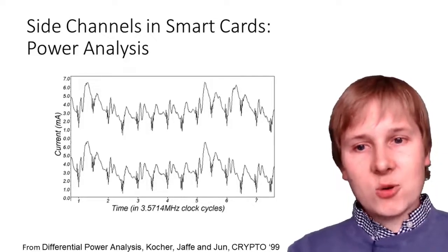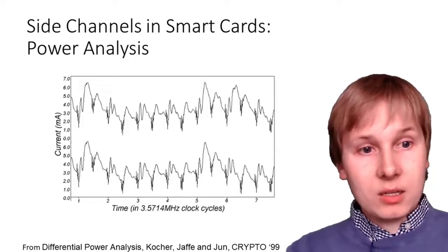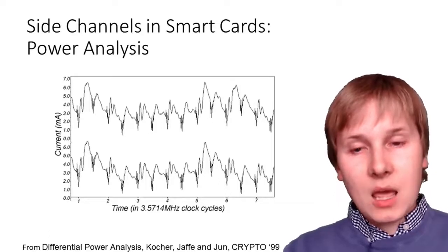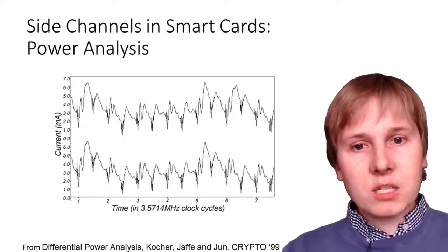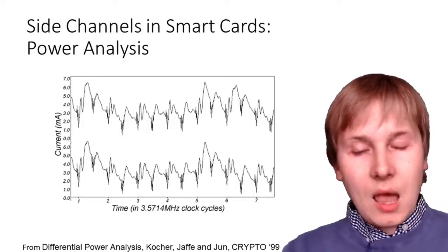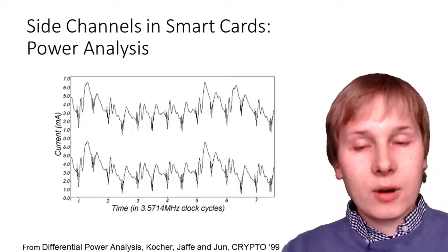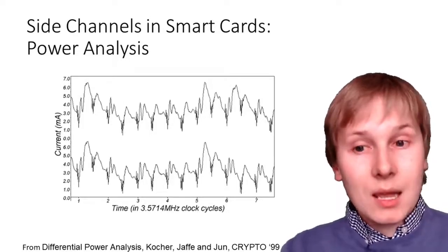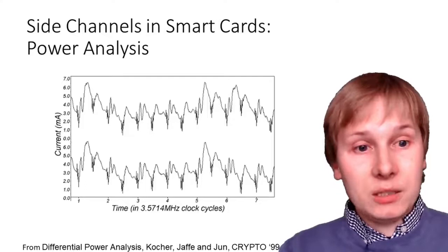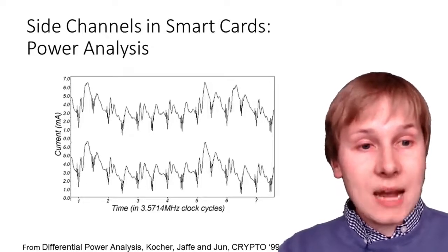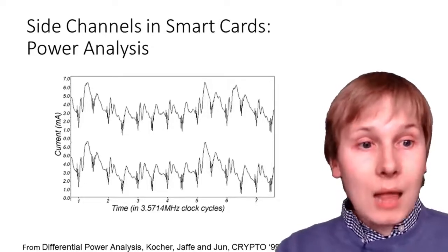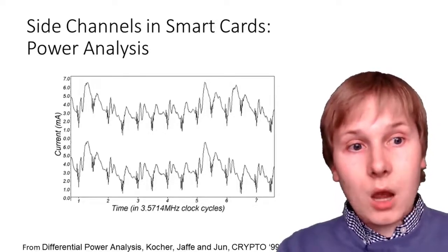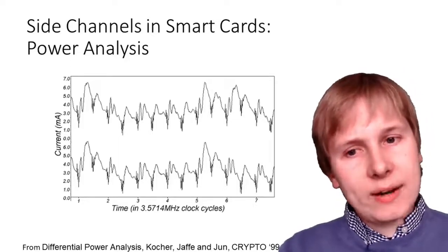That brings us on to some of the more advanced attacks that can be performed on tamper-resistant devices such as smart cards to trick them into leaking their key. If you have an infrastructure where all of the smart cards you ship store the same key, as is often the case for TV decoders for example, then a single compromise is often enough to create real problems. In that case, your smart card may be shielded in various ways to prevent direct readout of its secrets, but it will have to draw power externally in order to perform its cryptographic functions. So, you can do forms of power analysis.